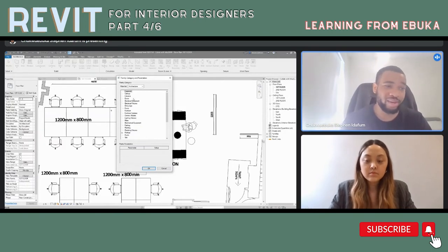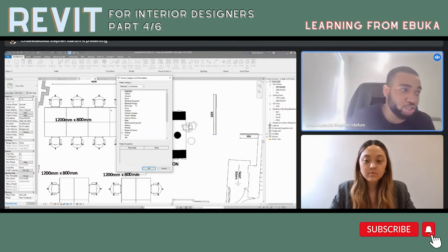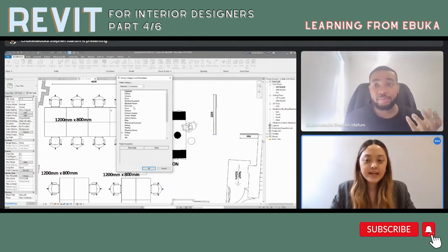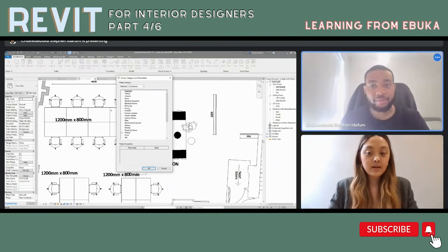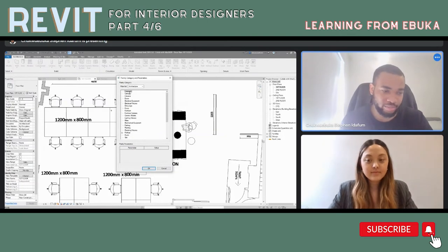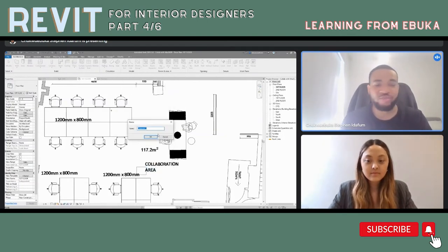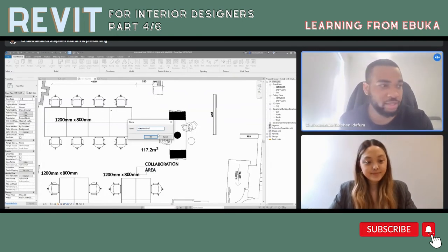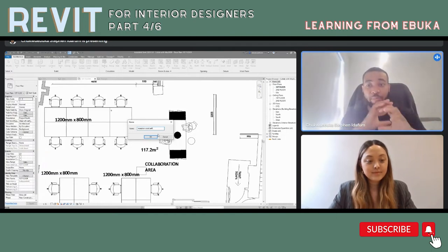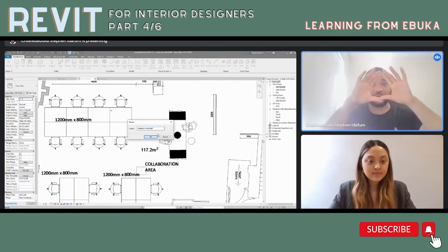For example, it's going to be a casework. Let's say I was modeling a light fixture, I would just scroll down to where I see light and click on it. This is just the name of the category that we want to create. So now I know it's a casework because it's a real world item. So click on it and press OK, and we can rename it Reception Desk. We're going to be making two parts, a base and a top.